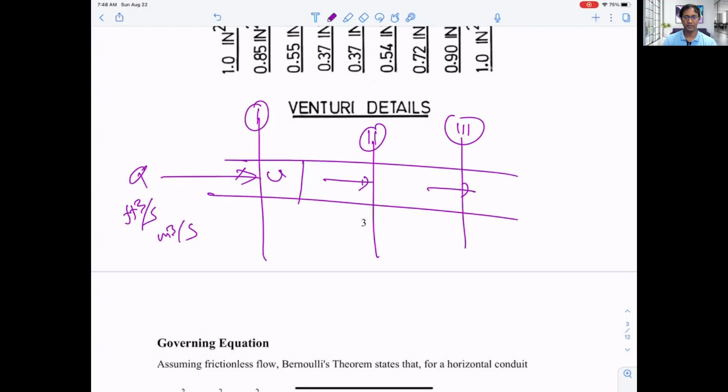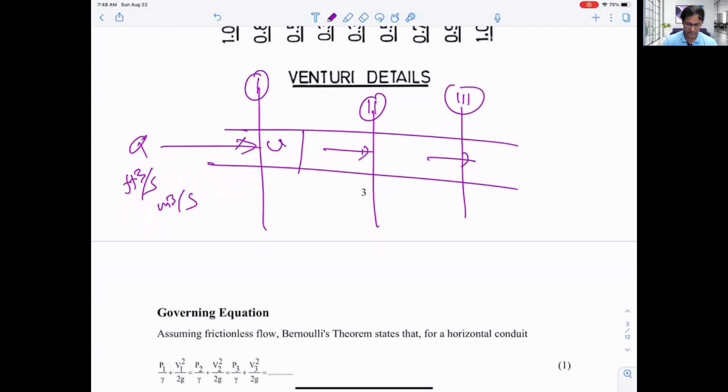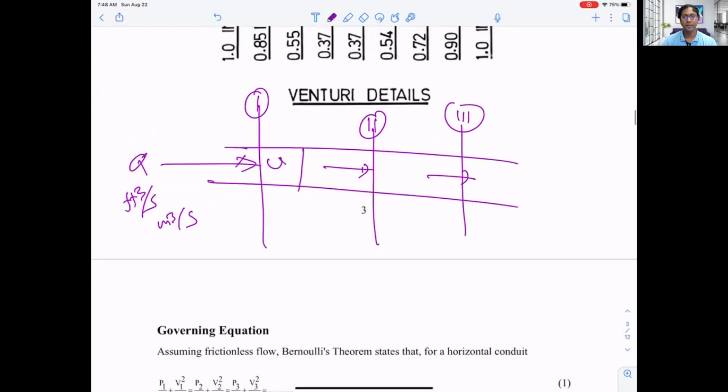So that's the reason that in a steady state condition, the total energy at every section along the path of a fluid flow will be the same. He's talking about the summation of elevation energy, pressure energy, and velocity energy. So we call it head, in terms of energy, here in fluid mechanics or hydraulics.